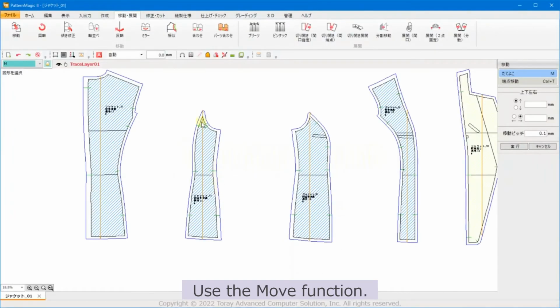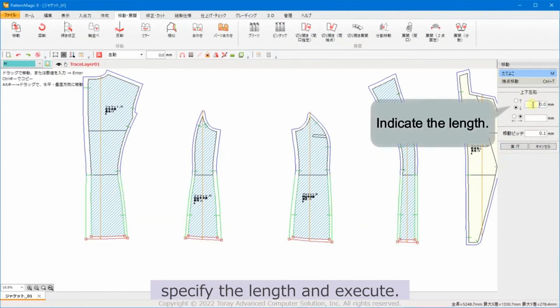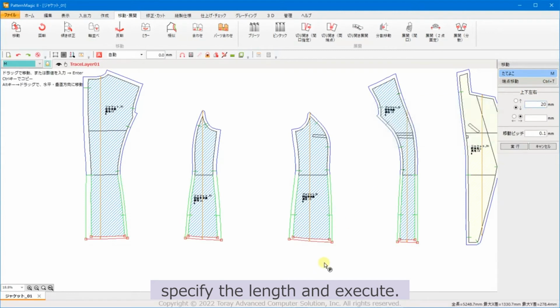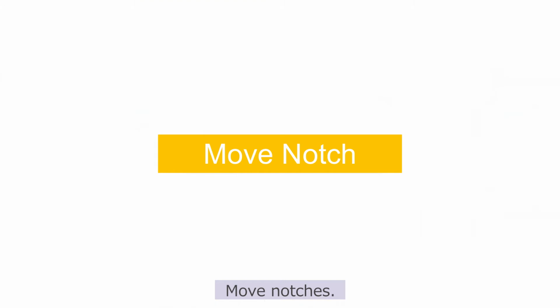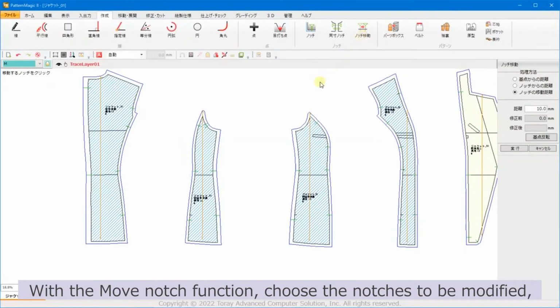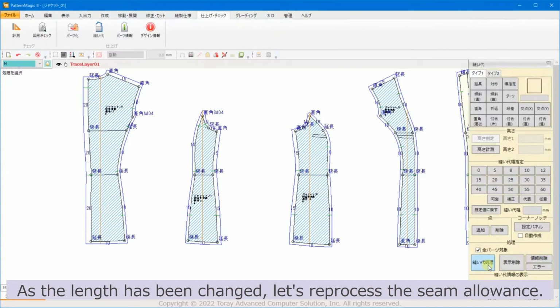Next, change the length of the garment. Use the Move function. Select the hems of all the lining pieces together, specify the length and execute. Move notches. With the Move Notch function, choose the notches to be modified, specify the distance to be moved and execute to move the selected notches. As the length has been changed, let's reprocess the seam allowance.